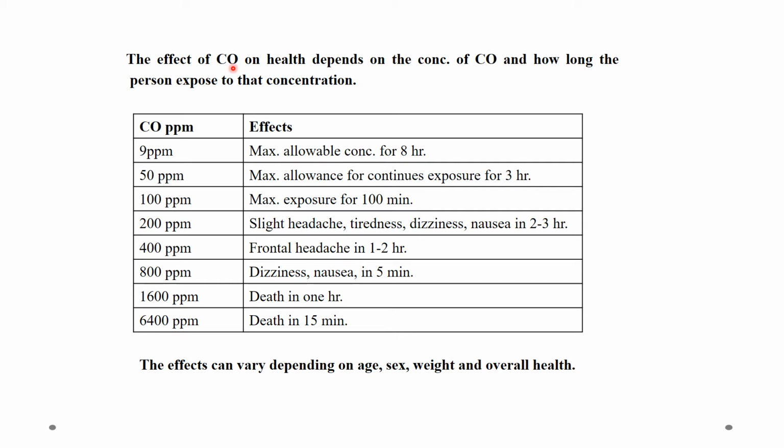The effect of carbon monoxide on health depends on the concentration of carbon monoxide and how long the person is exposed to that concentration. If the concentration is 9 ppm, then the maximum allowance is up to 8 hours of continuous exposure. If its concentration is 50 ppm, then the maximum allowance for continuous exposure is 3 hours.